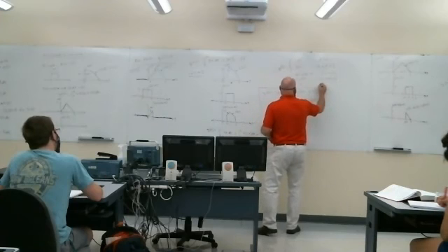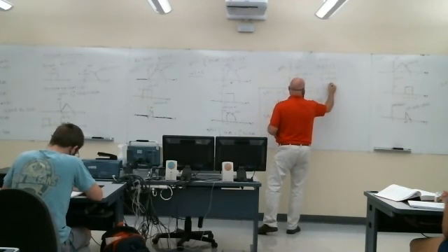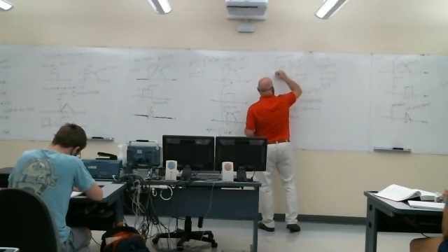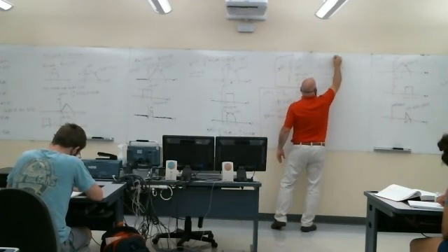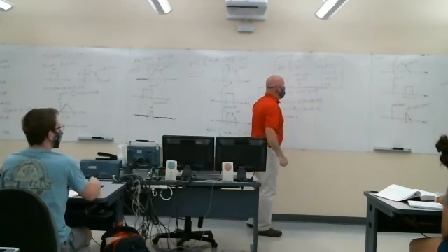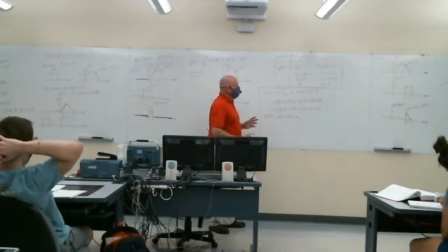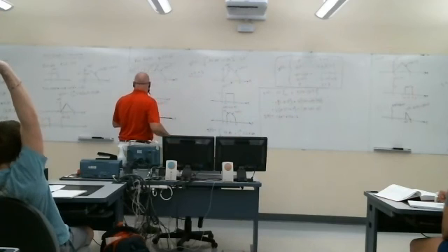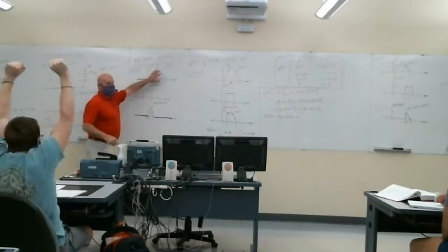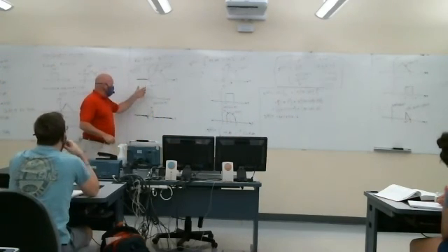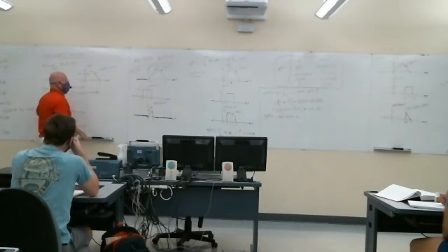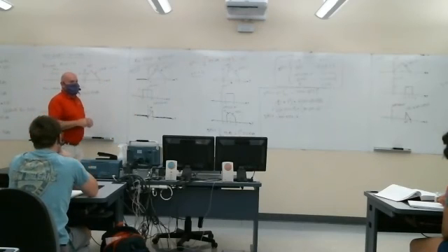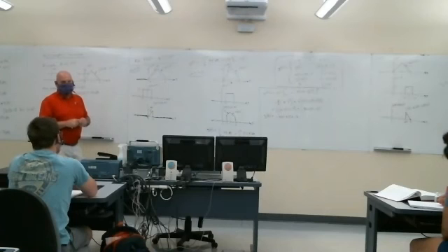So we're back to 0 for t greater than 3. So if we've done all this right, if we build a circuit that had this impulse response, this h of t, and we fed it this rectangular pulse here, that's the mathematical expression for the output.